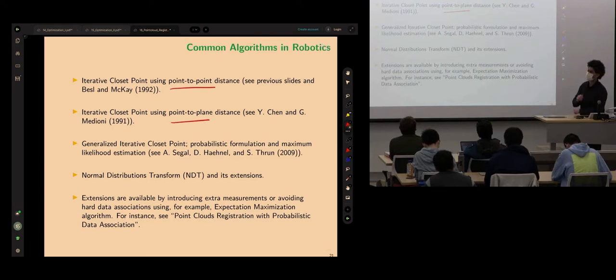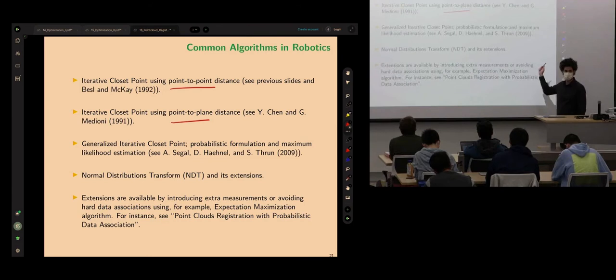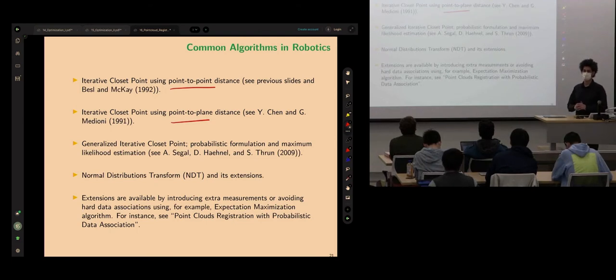Now, a lot of methods that solve the problem globally work with point-to-plane distance. When you switch to the GICP cost function, the covariances change the weight of the distance as the transformation changes, which makes it very difficult to solve within the context of the global solvers that you see in the literature. That's why they aim for point-to-plane ICP.